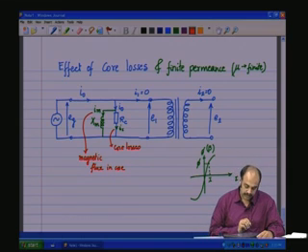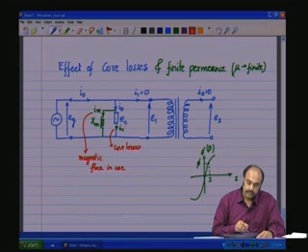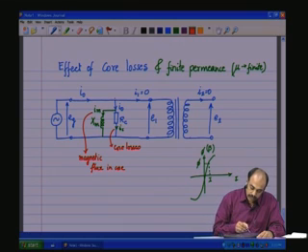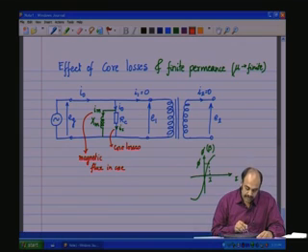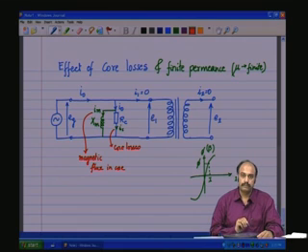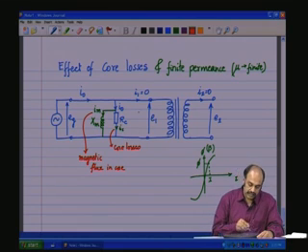How do we measure this? So, you see that Ic is producing a loss in Rc, Ic square Rc. So, the voltage across Rc and E1 will be in phase, which means Ic will be in phase with E1. E1 is same as Eg.